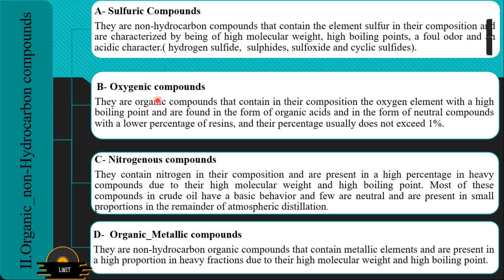Organic acids that contain from 1 to 6 carbon atoms make up most of the organic acid in crude oil. These compounds as well have harmful effects. They cause corrosion of equipment and oil units due to their acidic nature, and their effect increases with high temperature, as well as causing toxicity of the catalyst due to sediment as a result of a polymerization reaction.